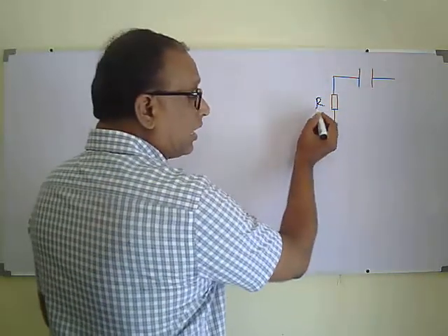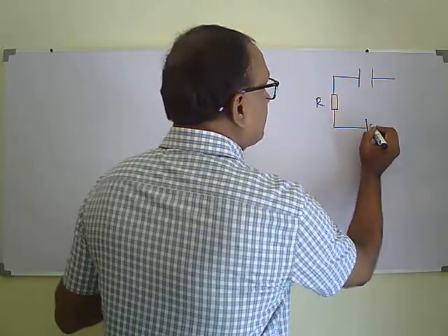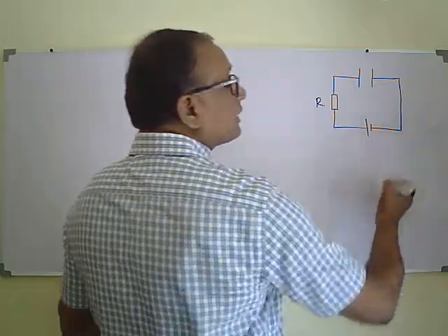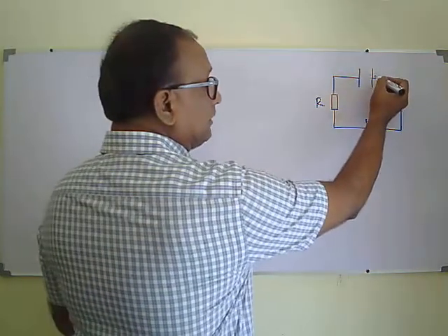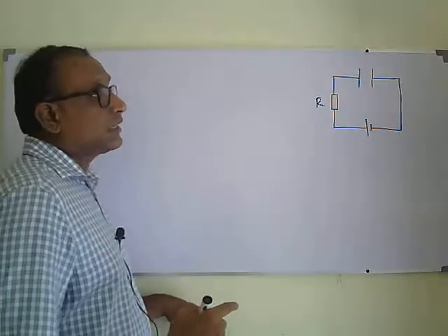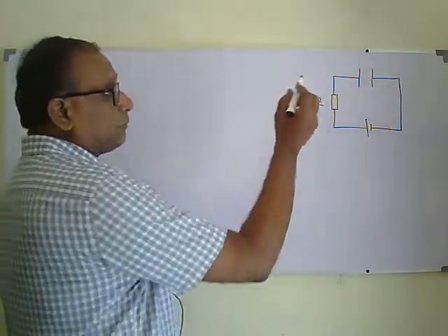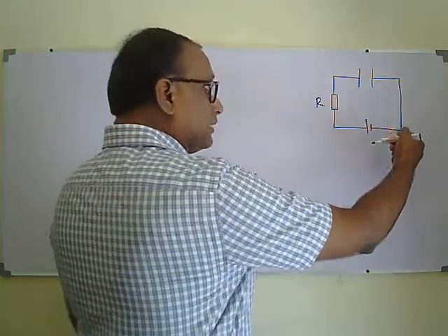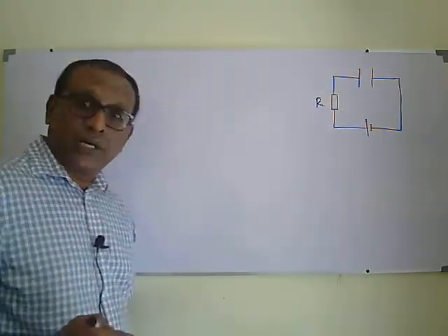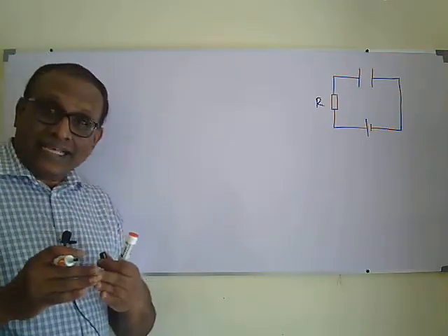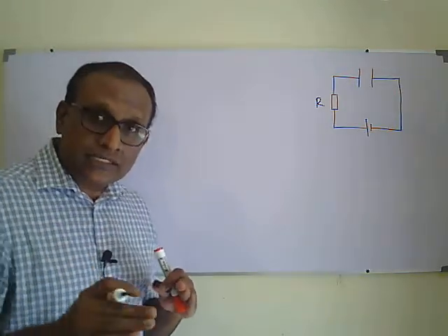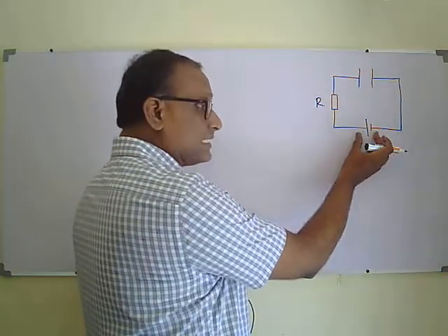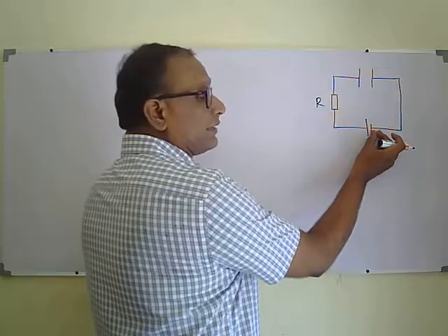That resistance R includes the internal resistance of the cell, the total resistance of the connecting wires, and the resistance of the terminals where the wires are connected to the capacitor, everything together, which I put as capital R. During the charging process, the same current flows through all the resistive parts of the circuit, so they are all in series. Even though it includes the internal resistance, I can include that resistance also.